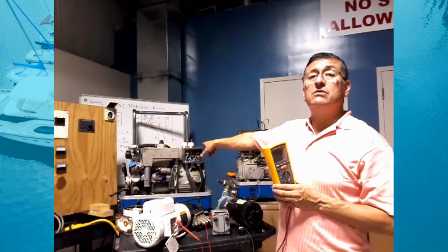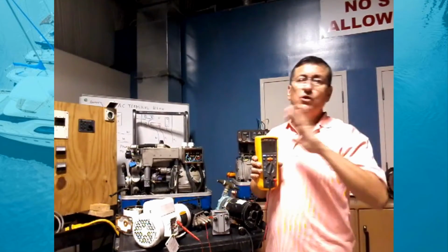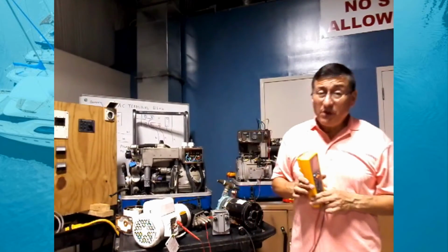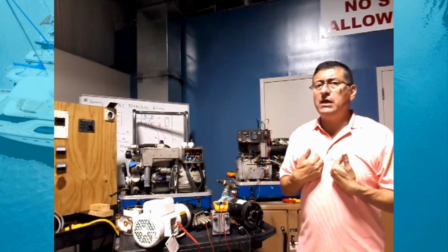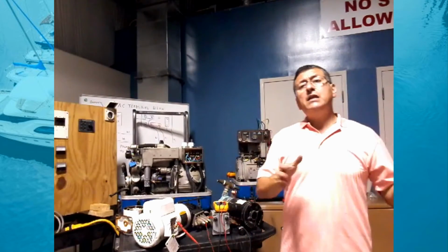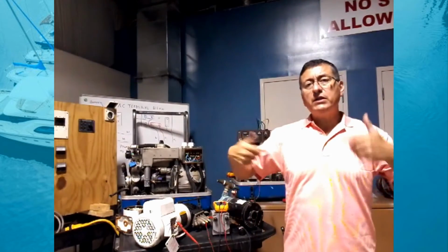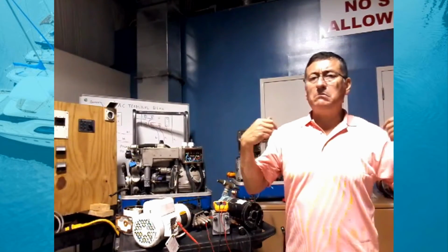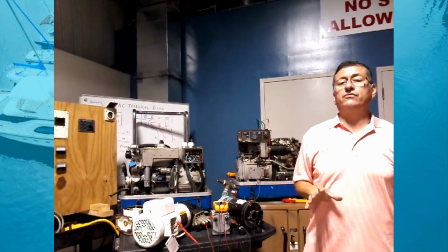Exactly the same with the generator. I am going to check phase by phase. If one phase is not good, you need to replace the back end or rewind the back end. Is it possible to rewind the back end? Yes, it's possible. But normally, in my experience, I explain to the customer, we can separate the back end and send it to the machine shop. The machine shop rewinds the back end, and I put it together again with the engine, and you have the generator for another amount of time.